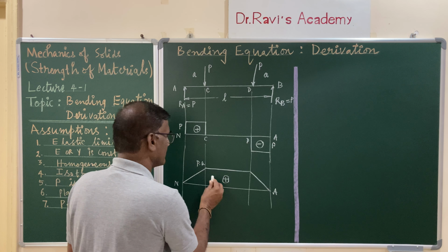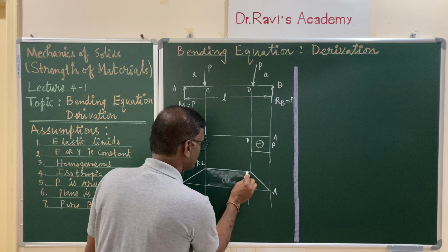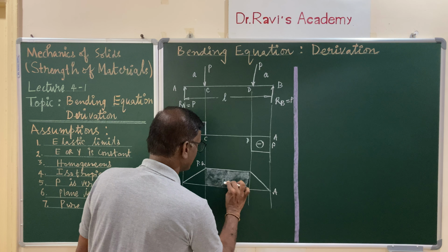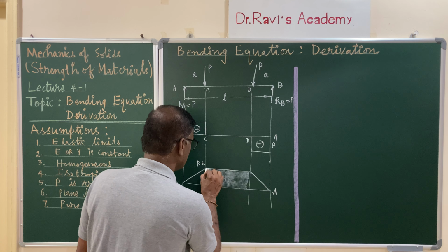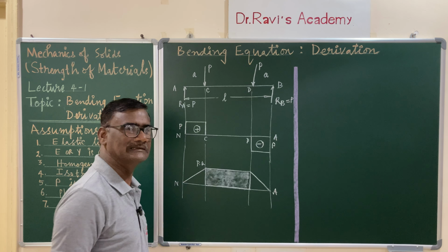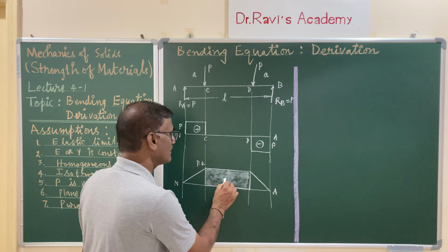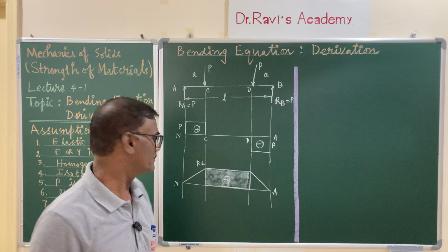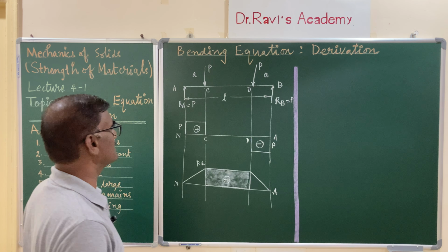This particular portion, remember, is called pure bending. You have only bending moment. It is something like, you know, pure milk without water. It is pure bending without shear force. Only bending without shear force is called pure bending, and that is one of the important assumptions.